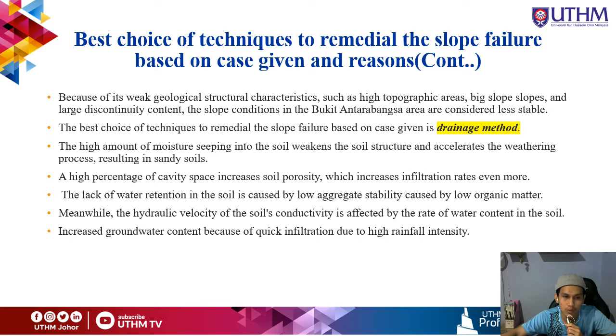Because of its weak geological structural characteristics such as high topographic areas, big slopes, and large discontinuity content, the slope conditions in Bukit Antarabangsa are considered less stable. The high amount of moisture seeping into the soil weakens the soil structure and accelerates the weathering process, resulting in sandy soils. A high percentage of cavity space increases soil porosity, which increases infiltration rates even more.